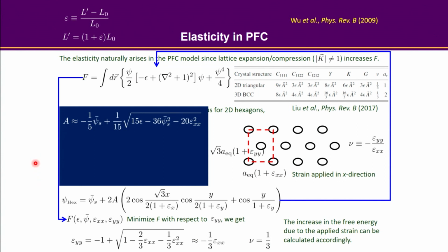It's pretty negligible. So you plug that back in here, and you just calculate the energy density of your solid with a little bit of manipulation. You are seeing that the stretched solid free energy density is equal to the unstrained solid free energy density plus some extra term and higher order terms. And that prefactor should be 1/2 the Young's modulus times epsilon xx squared, right? So that's how you get the Young's modulus equal to 2 times this prefactor. That's A times the amplitude squared.